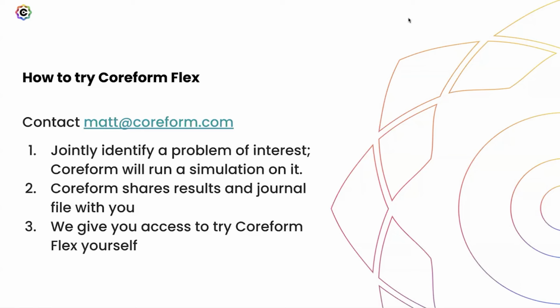All right. Another question from Yuri is, could your solver continue working with heavy mesh distortion such as non-uniform foam compression? Yes, this is an area where our customers specifically use our tool to accomplish just this. And with the smooth spline function, the deformation patterns, because of the smoothness, are also smooth and distributed more evenly across the mesh. What this means is that in general, you can distort our meshes, I would say maybe a factor of 2 or 3 more than linear finite elements for a given application.